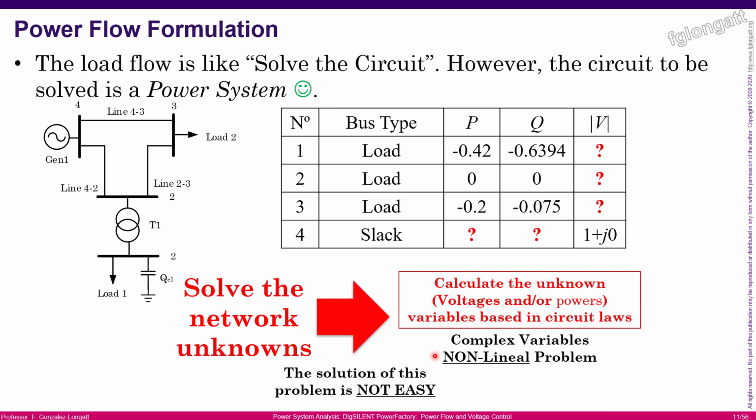That is one of the complexities of the power flow problem. But the second one is a bit more difficult, and it's coming from the rule that is defining the relationship between voltages and power. Voltages and power, they are a non-linear relationship. There is no linear relationship. I will explain that in a few minutes, in a few slides, but this is a non-linear problem. As a consequence, the main difference between the circuit analysis and the power flow analysis or load flow analysis is that here the relationship, the rule between voltages and power, is a non-linear relationship. Okay?